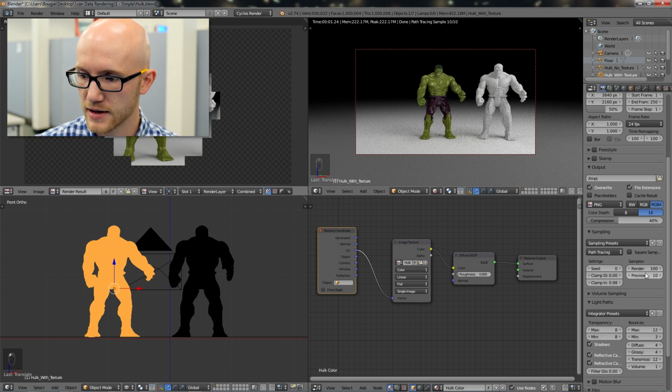And so that's the render samples. Preview samples is the number of samples it takes for this preview window up here in the top right. I keep mine set to 10. It's just enough to see basic shadowing and the overall layout.